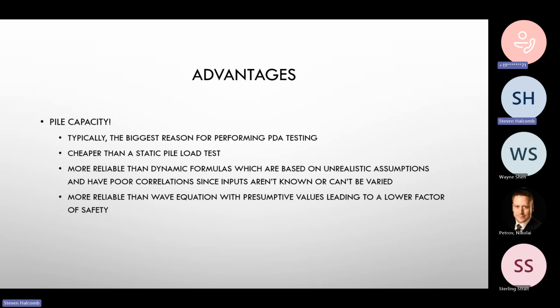And then the big one is pile capacity. That's usually like 80% of why we do this, is that verification for our driven capacity. I've done other projects with this, and I tried to find the photos of that Moose Run bridge. I couldn't find any of Ellen's photos of me doing this out there. I found a bunch of photos, but I didn't find any of me doing it. But on that one, we had to just look at the stresses. So sometimes we don't care, but capacity is a big one, because it's more reliable and doesn't have the assumptions that others do.